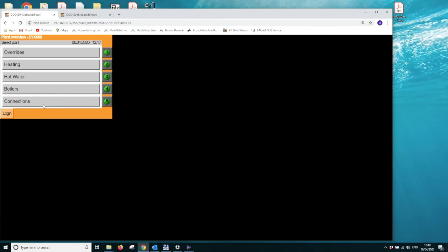The task at hand now is to identify why that particular building warm-up rate was achieved. So this could be due to a situation of building fabric. Maybe there was a window left open. Maybe there's a very ineffective radiator where the room sensor is located. Maybe there were problems with the plant. Numerous reasons, and that's what we need to identify.